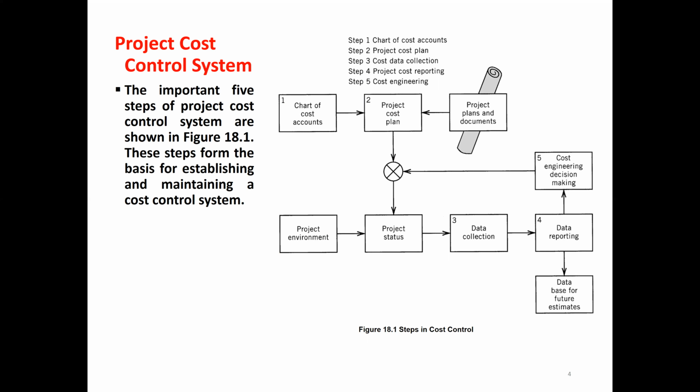So in the cost plan, we record the actual cost and the budgeted estimate about construction plan and schedule. We compare all these things to control the cost. So then we do the cost data reporting. So we prepare the project report and relevant record, and we discuss with the management.